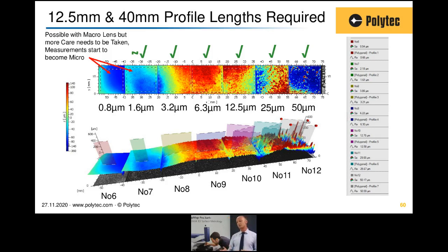The lines on the bottom give you an indication that if you had a 2D point profile measurement, the scan range needed, as recommended by ISO, for each of these surface types. For number 11 and 12, ISO recommends, because these surface roughnesses are very high, you need a 40mm scan length. And of course, I've had to zigzag the line across these surfaces, which is pretty impossible to do with a stylus type instrument.